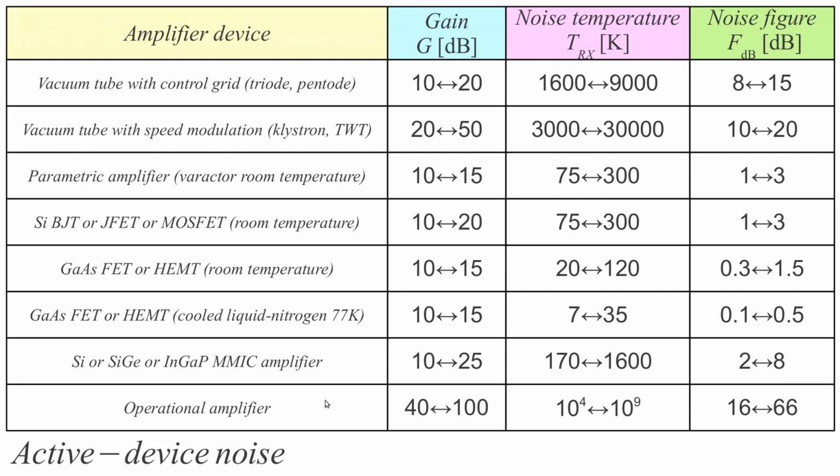Whenever low noise is in question, never use an operational amplifier. Even an MMIC amplifier, you may use in the second stage, not in the first stage. The first stage of your device should be a bare transistor with all matching circuits outside the transistor, all made out of reactive components. No lossy feedback in this amplifier.